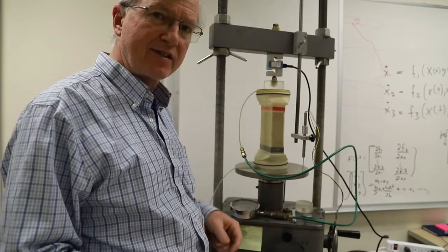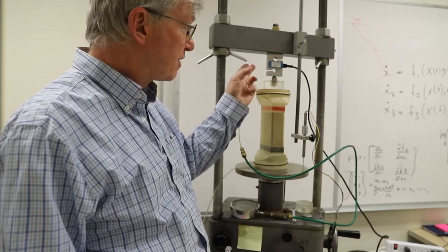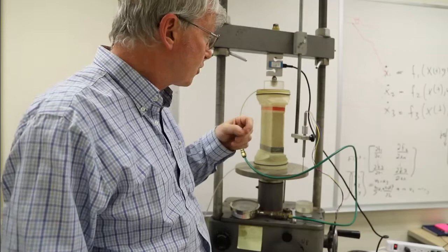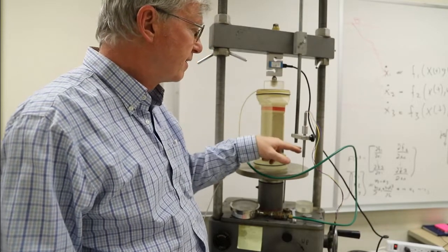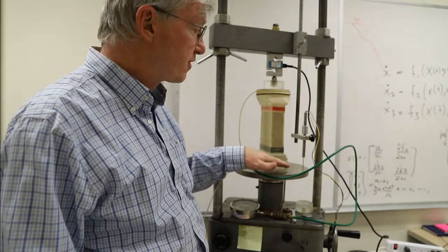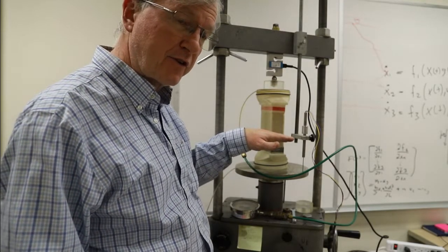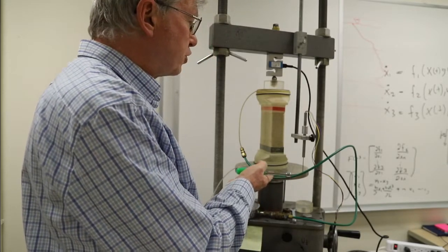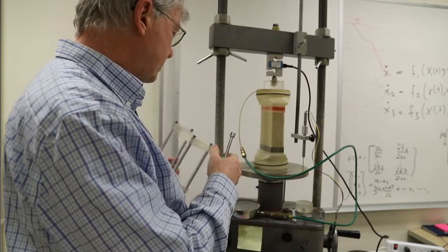So we have our dense plane strain specimen here in the device, and it's set up very similarly. It's important to have it centered. We have the load cell above on the crossbar. We have a small gap still between the sample and the load cell. The LVDT is here. Again, it's going to measure the displacement of the table as a function of time. Of course, that table is pushing the sample up against the load cell to run the test.